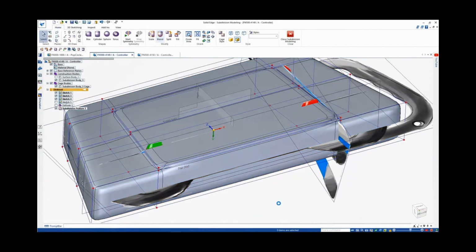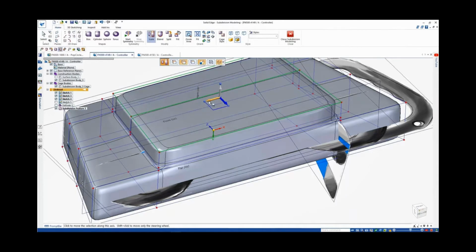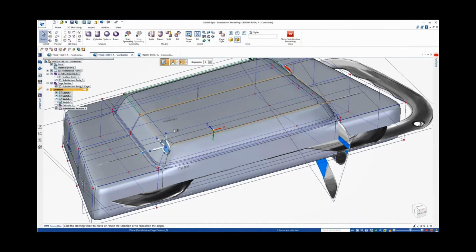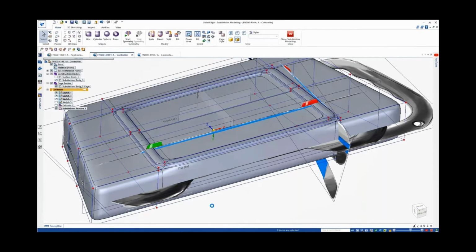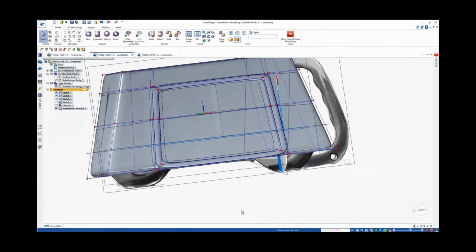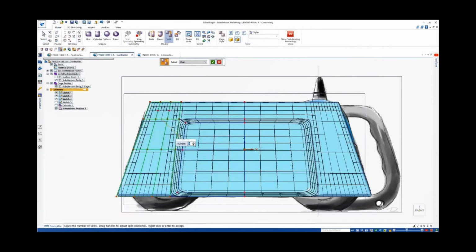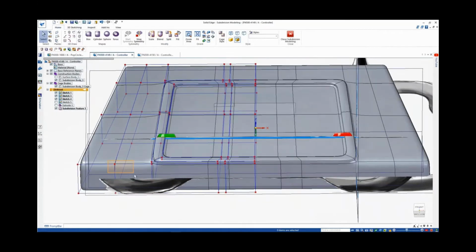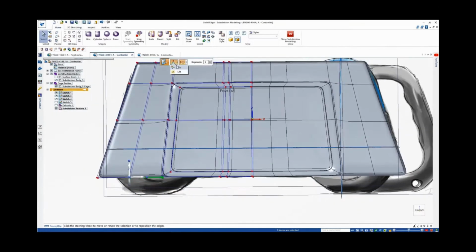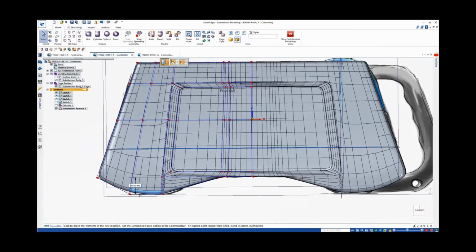And while you may expect to have only smooth blends, that's not the only case in Solid Edge. You could choose to have sharp blends if you would like. Then to make the cutout for the screen, it's just a matter of pushing and pulling to get the desired results. A lot of parts have to be designed symmetrically. Well, with subdivision modeling, you can see just how easy it is. And if you're familiar with synchronous technology and the steering wheel, it's not a problem at all.